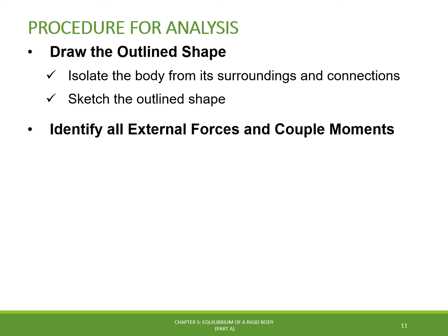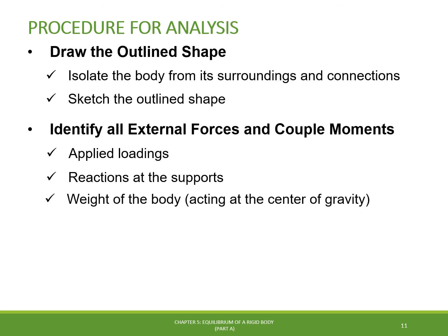The next step is to identify all known and unknown external forces and couple moments acting on the body. They are generally caused by applied external loadings, and reactions occurring at the supports or at points of contact with other bodies. For this, always refer to the support elements shown in slides 6, 7, 8, and 9 of this video presentation. And we also have the weight of the body, which will always act at its center of gravity.